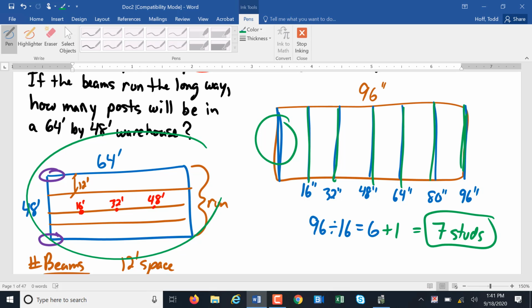I always liked working with a 3, just the 3/8 bar bends. You can bend that by hand. The number 4, the 1/2 inch, I always took 2 pipes and usually a post hole in my post pocket in my trailer to bend them. But the number 6, the 3/4 inch, you have to have a bender to do that. Or a torch. They kind of frown upon you heating up rebar.